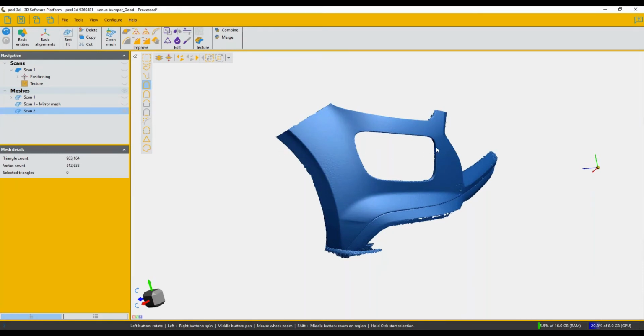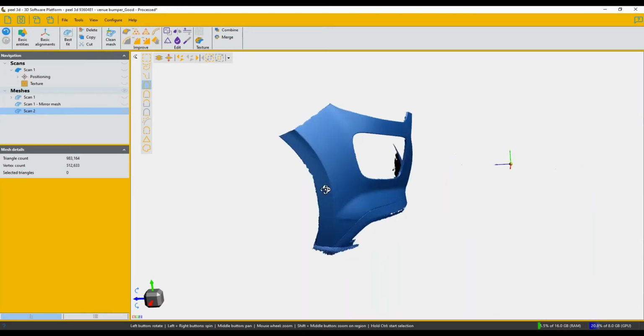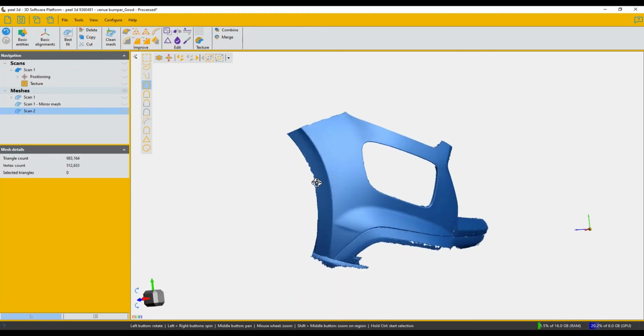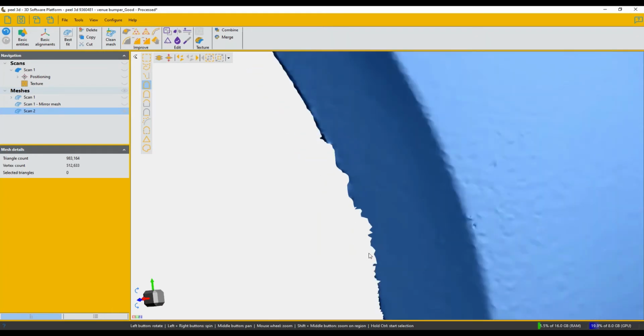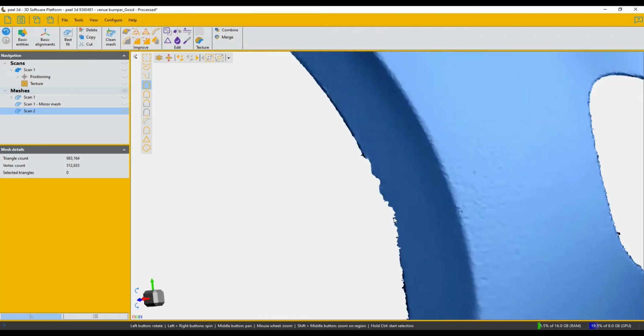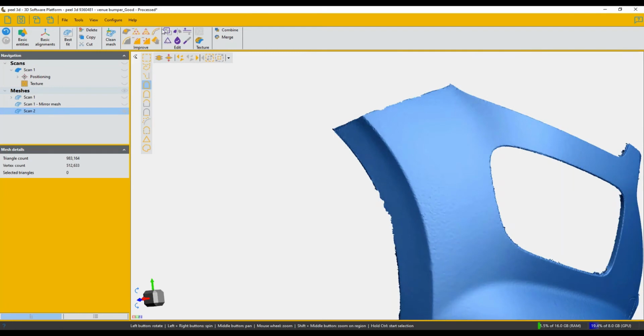Once we've done that, we can then start to process and condition the boundary of the mesh. We can fix it up to smooth it out. We want to make sure that we have a very smooth boundary. If we were to try and flatten something like this, then our pattern would have this characteristic there, so we want to smooth this out. And the way we're going to do that is we are going to use the Edit Boundary tool.